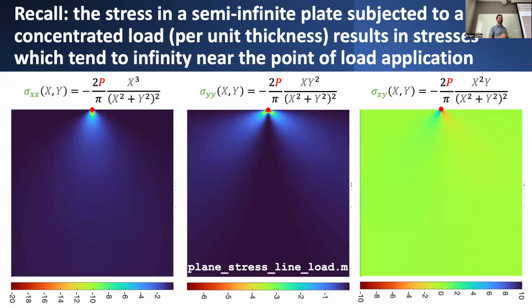It's hard to think about it. Basically the only assumptions that we've made in coming up with that strain displacement relationship, if you recall, which is equivalently, if we're assuming that the strain field comes directly from this relationship, then we automatically satisfy compatibility, is this.